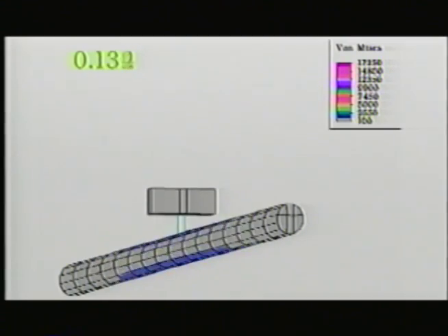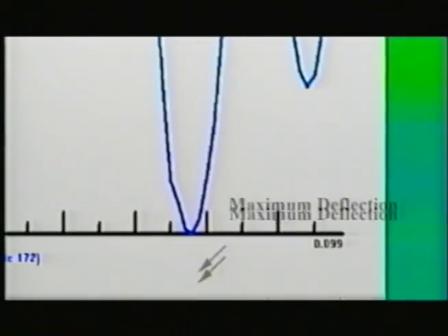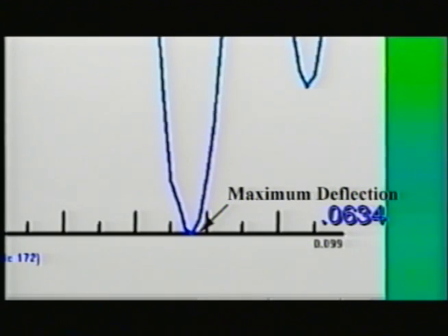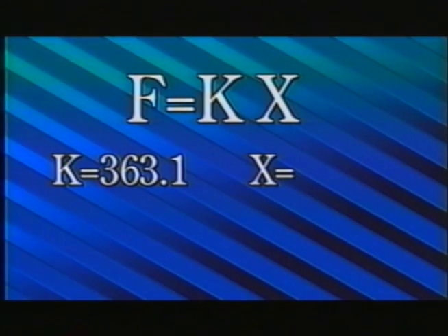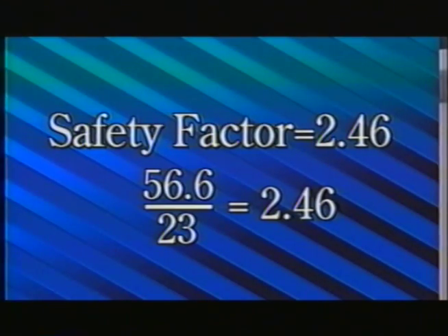Now the process is taking place. And the deflection is 0.0634. Plugging this into the equation for force, we get about 23 pounds. So the safety factor is only 2.46.